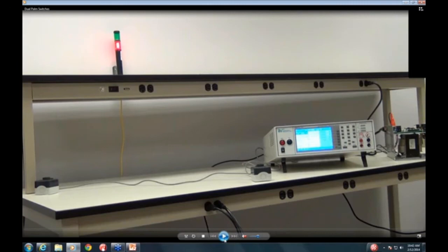What you can't see in this video is I do have insulation matting on the floor there. So even though I'm using these other safety measures, I'm still using my insulation mat. And this particular lab, the door that goes into the lab, has a danger high voltage sign on the door. The nice thing about the lab is I can keep it completely enclosed off from everybody. So that really mitigates the hazard for anybody else. And only myself and a few other people are qualified to go in here and work with this equipment.